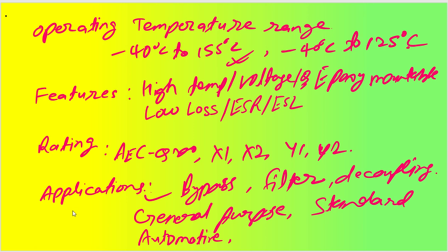There are some manufacturers which are giving us applications also. So they can tell you that it can be used for bypass application or filter application, decoupling applications, or general purpose applications, or like standard and automotive applications. Okay, so if you have an automotive application, the rating must be AEC-Q200. Okay, so that's the understanding.